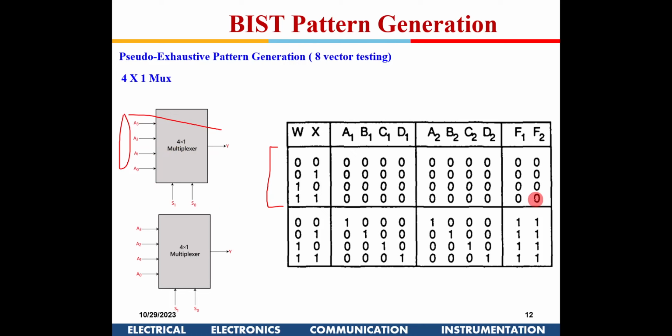So it tells. Then again, what I do is I put a 0 0 here, and I give 1 only to the 1 input here, and check the output here whether I am getting 1. Others are zeros. So if others are zeros, I can also confirm that this 1 is not getting shorted internally. This 1 is coming out here, and within the mux, this 1 is not getting shorted to ground. That is the reason I am putting zeros here. And I am still getting a 1 output. So it indicates that when I give 1 here, I get 1 here and 0 here, so this 1 is not internally getting shorted.